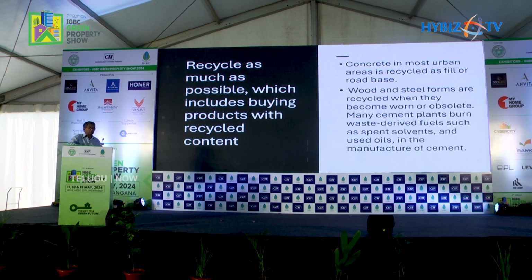Recycle as much as possible, which includes buying products with recycled content. Concrete in most urban areas is recycled as fill or road base. Wood and steel forms are recycled when they become worn or obsolete. Many cement plants burn waste-derived fuels such as spent solvents and used oils in the manufacture of cement itself.